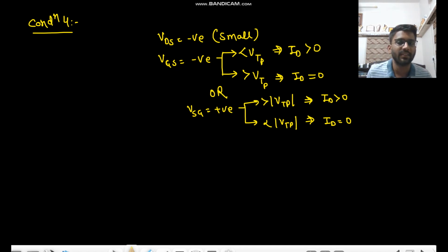Now VDS we have applied. If VDS is applied, then the current will be finite, that we have already shown here. Okay, because we have applied the negative potential at drain, that will attract the holes and the current will be finite. Okay, but the VSG value is the controlling.